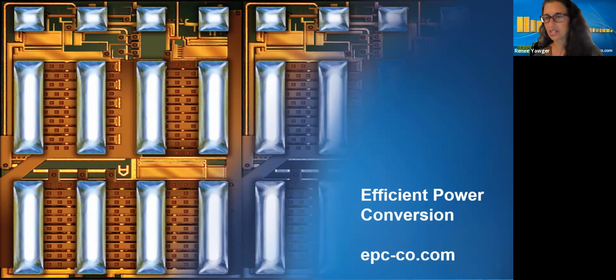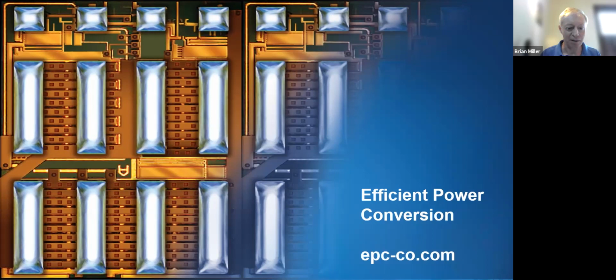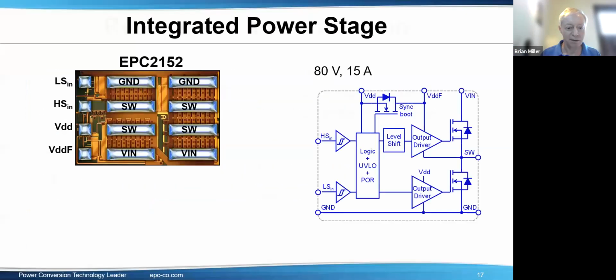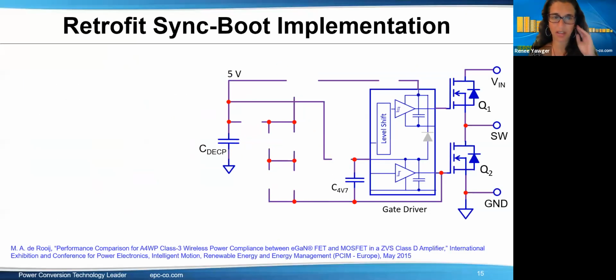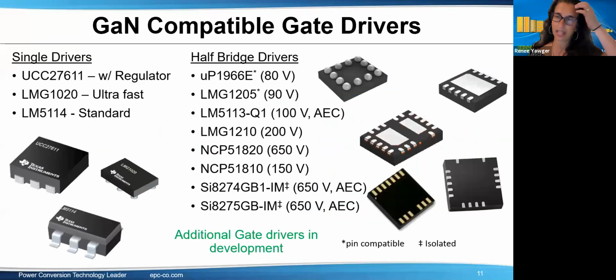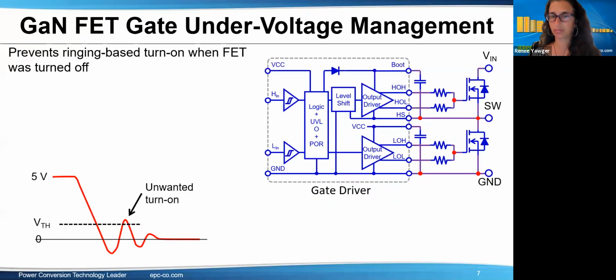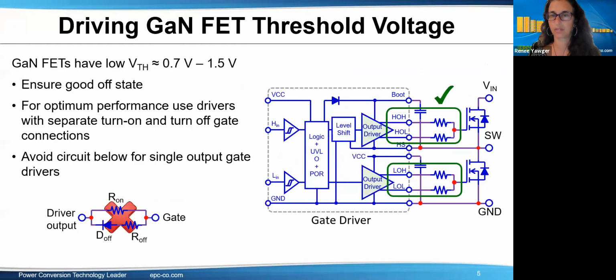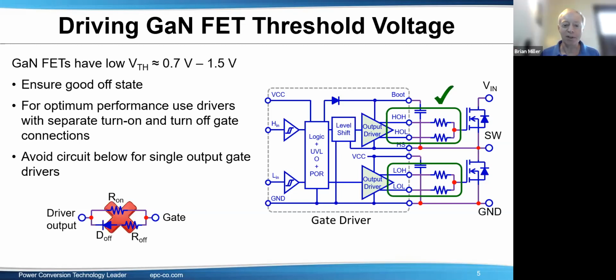Okay. So this question is specifically on slide 5. It says, is there any better option rather than using a diode with RG off while using single turn on/off gate drivers? Yes, just one single resistor is good.